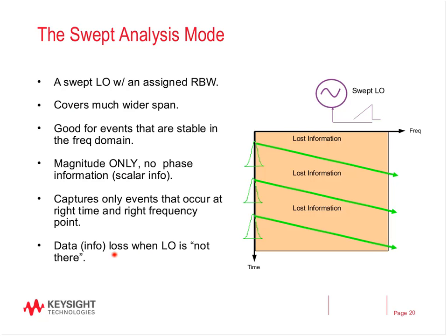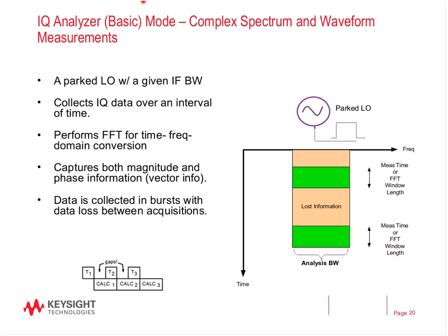There's a lot of lost data. So basically, you're hoping that you capture the signal. In this case, applying the POI information we talked about above could help. But in this situation, there might be better tools. So one of them is to do a wideband capture if you're operating in band. Maybe you want to look at your in-band spurs.